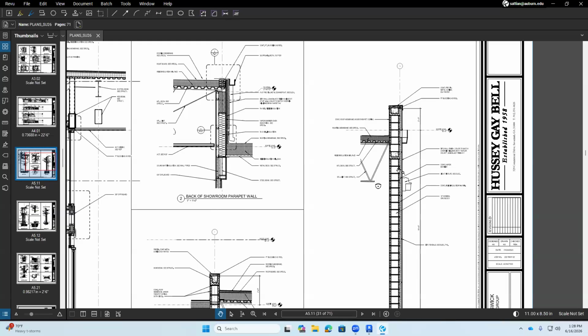So what happens is there's a door right here. Well, what's above the door? There's wall continuing. Where's the weight of that wall going to go? We want that weight of the wall to come to this side and this side, not directly on the door. So we put a beam just above the door, and we call that a lintel.